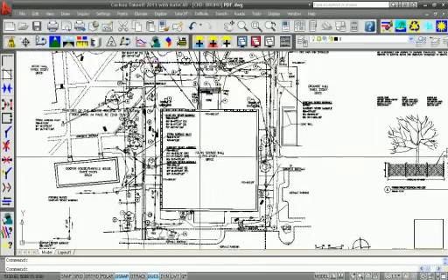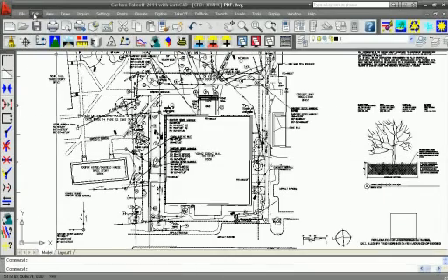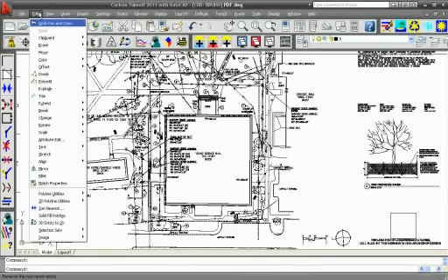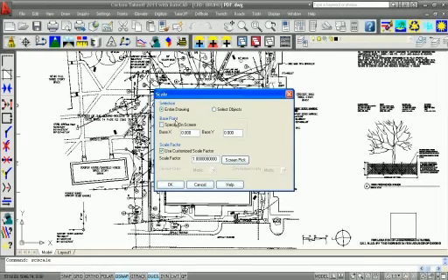Yeah, so we're looking to scale this drawing. The process to scale now is a lot simpler than it was before. It's just under Edit, 2D Scale. Now a dialog comes up that makes figuring out the scale factor on the drawing a lot easier. So what do you want to scale? The entire drawing or certain objects in the drawing? Just right in this PDF, so we want to scale everything. Use customize scale factor on this job. That's what we're going to do.